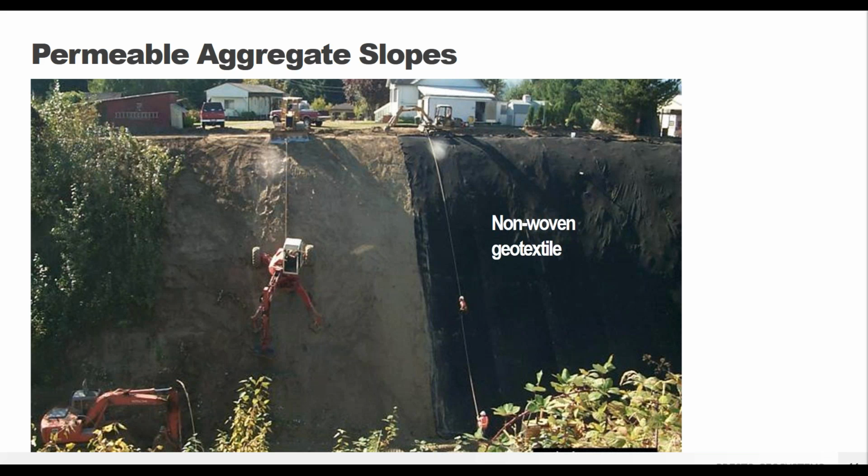A stone infill and a soft soil slope are going to be very different materials. And so having a geotextile as a separation layer can be a benefit to make sure you don't have mixing of those two materials. If you have soil infill and a soil slope, two really compatible things, you don't necessarily need that separation layer.